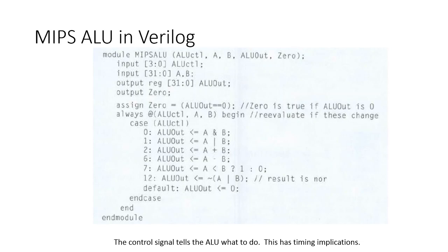This is how, I touched on it briefly last time, you would implement this in Verilog and VHDL. This is the additional statement I said that we would need, an at always, so that these values are always available. This is cool, because for the purpose of implementation, there's no propagation delay, so this isn't sequential logic, it's all combinational. So putting this always at means anytime this input changes, or this input changes, it immediately reevaluates it,